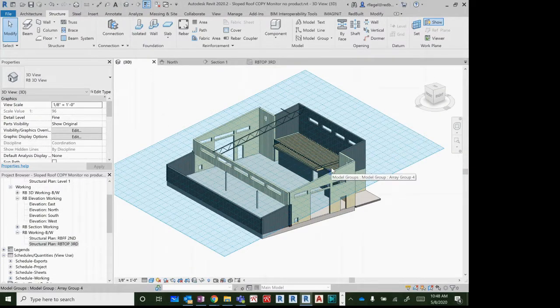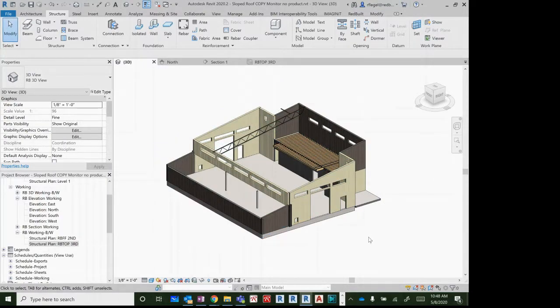So you can see reference planes are the fast and easy way to draw monoslope roof systems. If you want to do a multi-slope or a warped roof, I recommend reviewing Guy's original video on warped roofs. That's probably the most effective way to do varying slopes. But for monoslope, set your reference plane, go into a section view, draw your trusses, everything should line up.